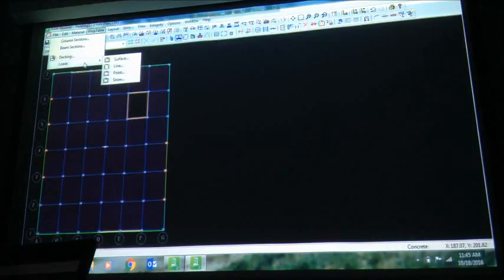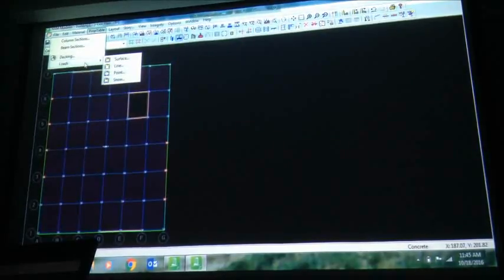Now there are a couple of different loads. You can use surface loads, that means PSF loading. You can use line loads, mostly those line loads are wall loadings or something. You can use point loads, basically if you have a machine or something, a huge load, you can say it as a point load, or you can use snow loads. Obviously it's on the roof. Also snow load comes with the drifting issue.